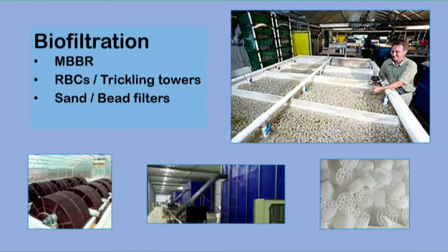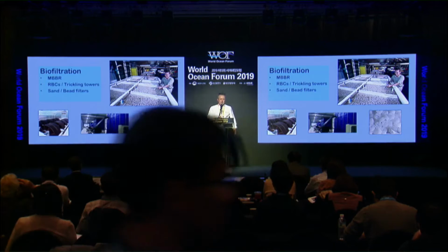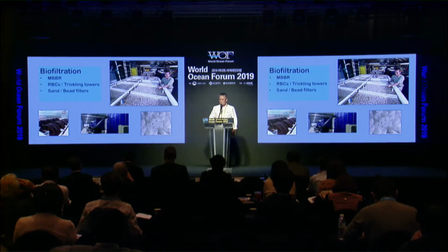Then secondly, we have ammonia removal, right? And so, like you saw in both the presentations, Mr. Hahn and Mr. Heinrich, the moving bed reactors, but there's other things besides moving bed reactors. So you can use rotating biological contactors. You can use trickling towers. Mr. Heinrich had some of those in his presentation. And you can use sand and bead filters.